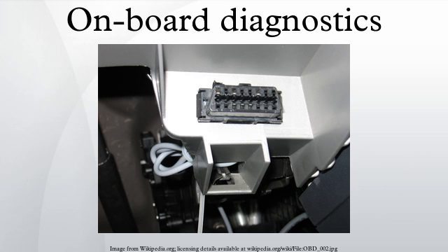Emission testing. In the United States, many states now use OBDII testing instead of tailpipe testing in OBDII-compliant vehicles. Since OBDII stores trouble codes for emissions equipment, the testing computer can query the vehicle's onboard computer and verify there are no emission-related trouble codes and that the vehicle is in compliance with emission standards for the model year it was manufactured. In the Netherlands, 2006 and later vehicles get a yearly EOBD emission check.